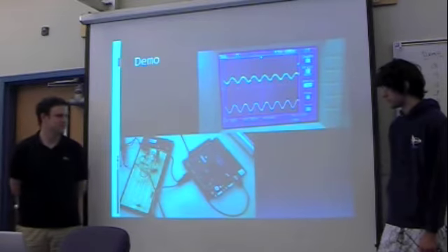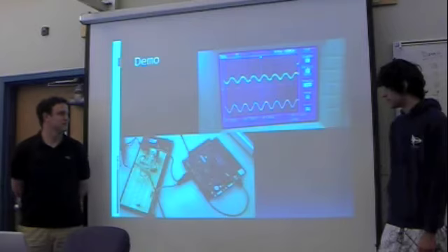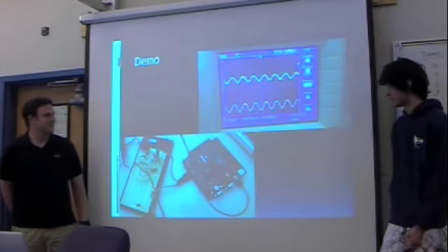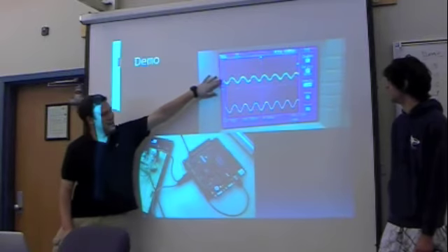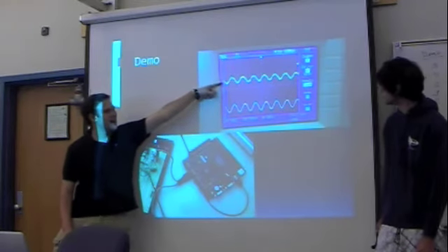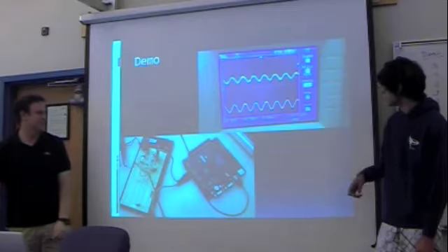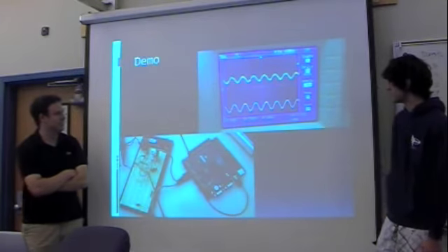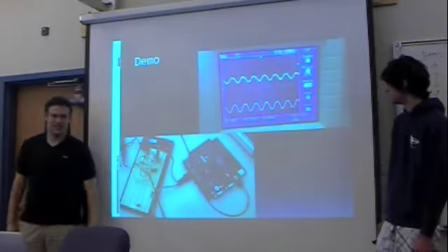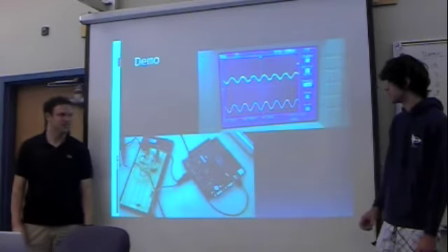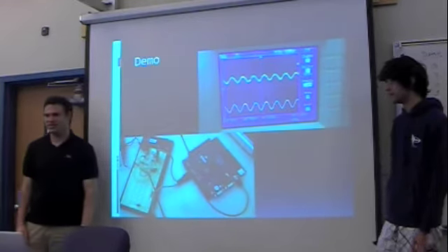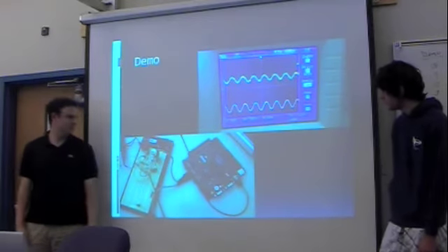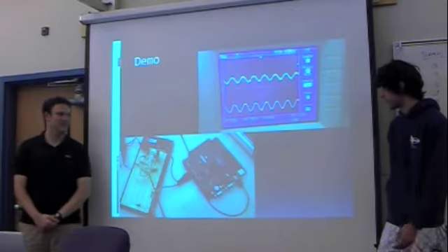Change the sampling rate for fun. The next is testing the filter to see if it works like a filter is supposed to, which I'm glad it did. That's what is coming out of the DAC, after the filter. If you zoom in on this, you will see it has a 26 kilohertz noise, which you couldn't hear, but for some reason it caused the speakers to sound funny, so probably just interference.